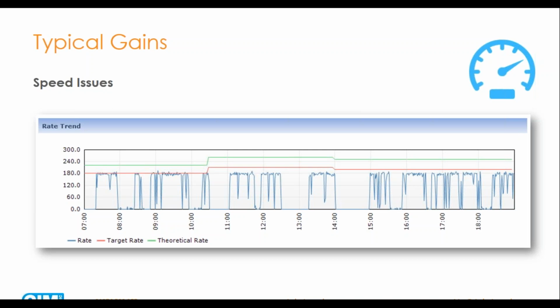Now, I would perhaps go one step further and say, for clarity, let's call that an availability loss. And with performance losses, we'll just consider performance to be speed-related issues, and it keeps the boundaries quite clear. And if you're very early on in your OEE journey, it's quite good to keep things simple and understandable in that respect. So by measuring the performance in real time accurately through a sensor, you're able to determine the speed of the line every 15, 30 seconds to 1 minute.